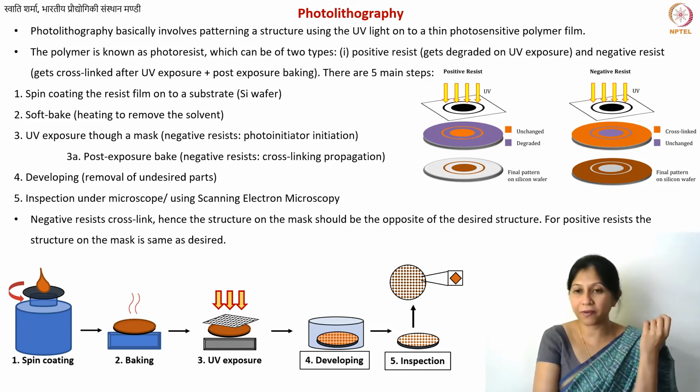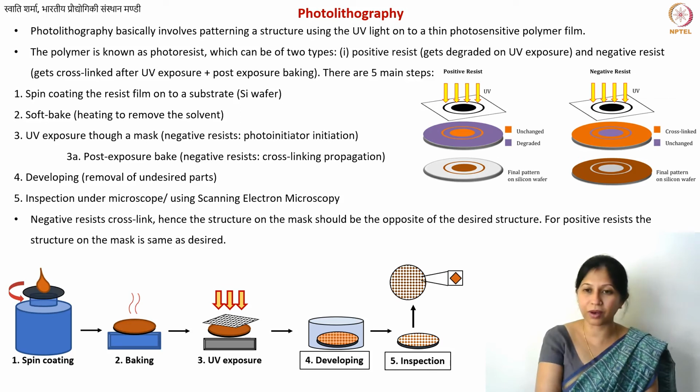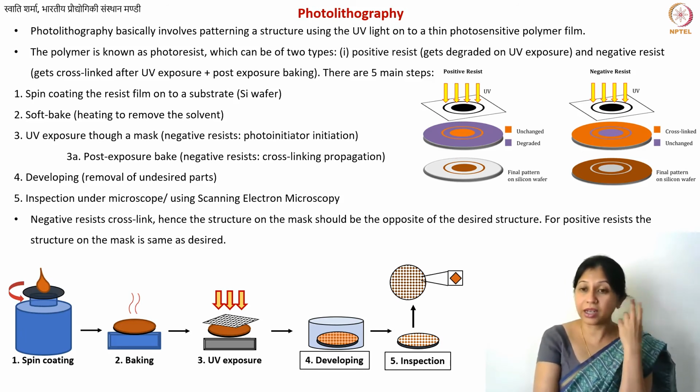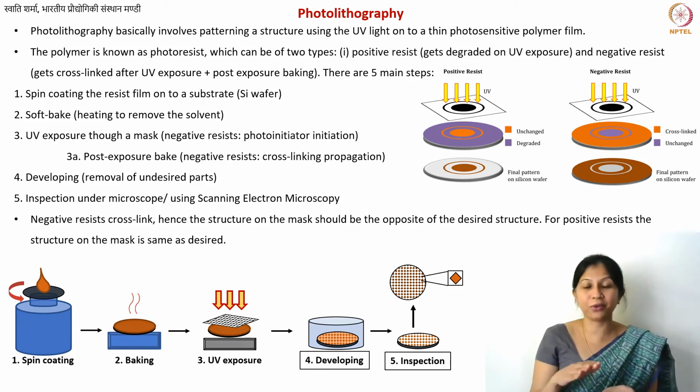In the case of silicon wafer, silicon based technology is very widely available, because it is used in the IC industry. So the thin film technology for silicon wafers, these spin coating techniques, and all these machines are easily commercially available. And the best thing about silicon, also for its popularity in the IC industry, is that you can grow films on top of it, silicon oxide films or silicon nitride films. Silicon oxide can be easily grown just by keeping the silicon wafer inside a